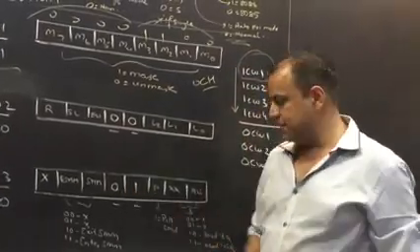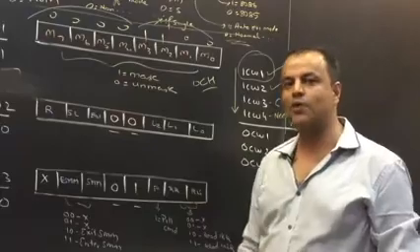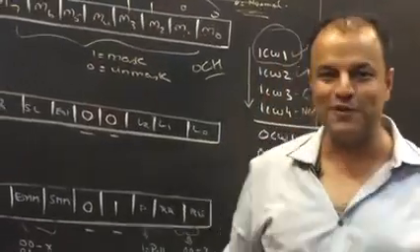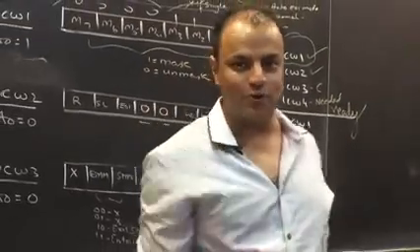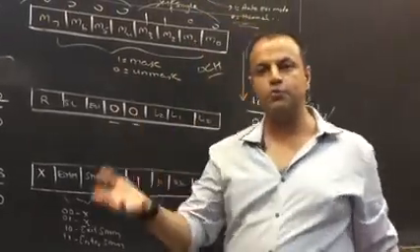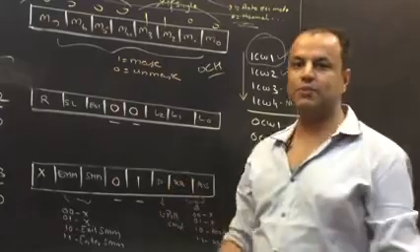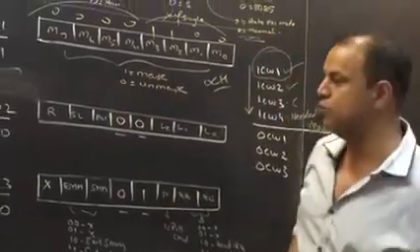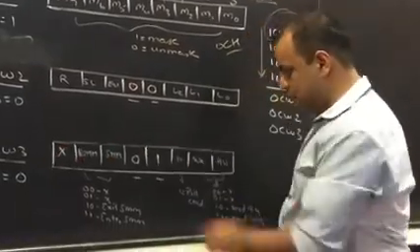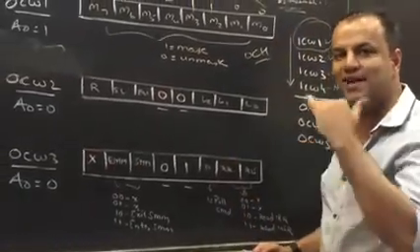These two bits are permanently 0, 1: P, poll command. Remember what is polling? Opposite of interrupting. Polling means asking. Instead of you giving me an interrupt, I will ask you, do you have a doubt? So instead of 8259 interrupting, the MUP will poll 8259 and ask whether there are any interrupts. So how do you poll? By giving a poll command. Is there a command by the name poll command? No. OCW3 with the P bit as 1 acts as a poll command.